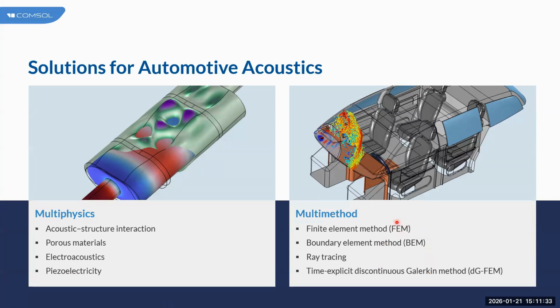It is primarily based on the finite element method, but when you are modeling very large acoustic problems, acoustic radiation or scattering problems, you can also use the boundary element method. And you have ray tracing to model acoustic wave propagation over very large distances. And for time domain simulation, to accelerate the simulation, you also have the time explicit discontinuous Galerkin method as well. So now let's move on to take a closer look at these multiphysics and multi-method approaches.